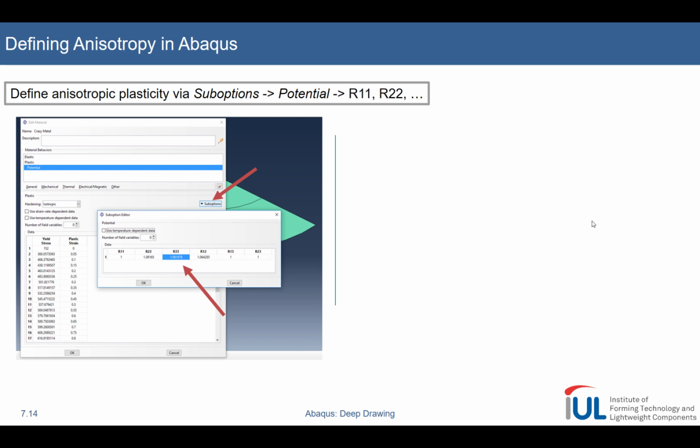Just for now, you will see some preliminary results. So I set up a quarter-symmetric simulation in Abaqus Standard defining anisotropic material behavior. About the details that would yield these results, I will talk about in the actual implementation video. So first on, how do we define an anisotropy in Abaqus?